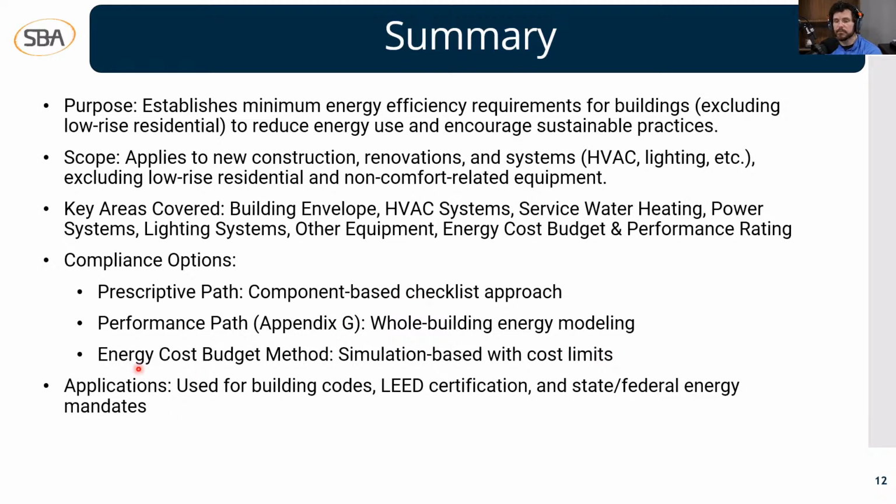And some of the energy modeling programs that we use, as I mentioned, were eQuest, EnergyPlus, Trane TRACE, or Carrier HAP. A lot of these can do the job, and it's really cool to see how all the systems get built out, and then you insert all of your information into there, whether it's the base of your design for your hot water temps, your wattage per square foot on your lighting, your R values, your U values.